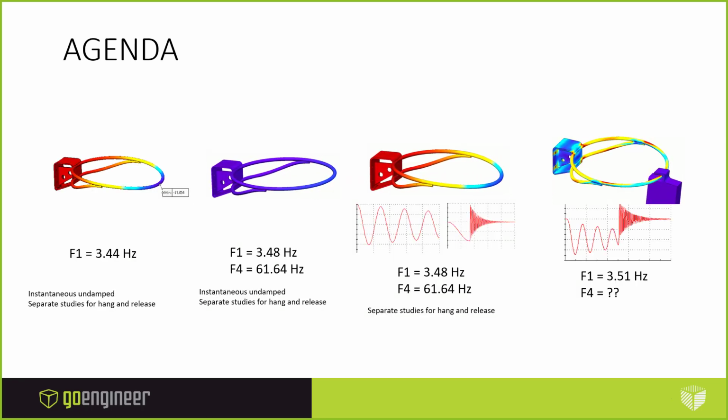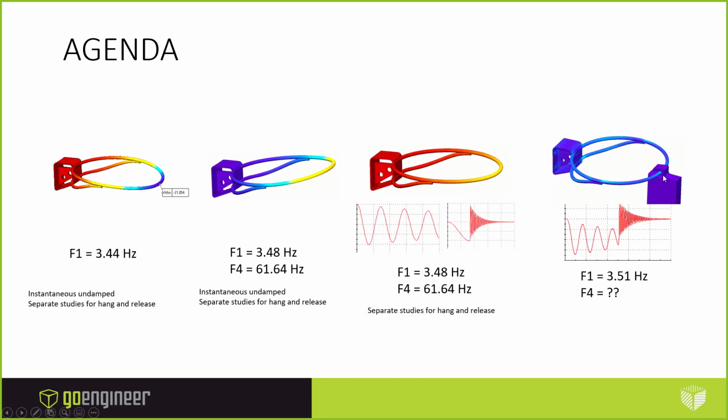But this animation I'm showing you here is more in line with what I just ran, or what I just showed the setup for. I turned on that, I stabilized this thing, had it initially starting at that position and comes down and up. So if I do that hand calculation, I can derive the natural frequency, 3.51 hertz.